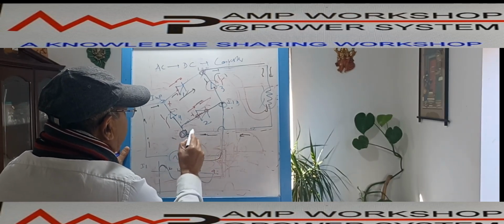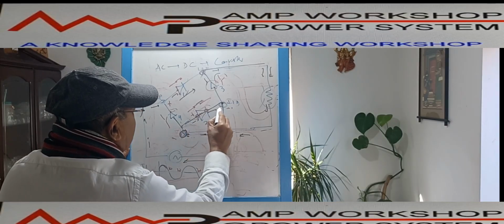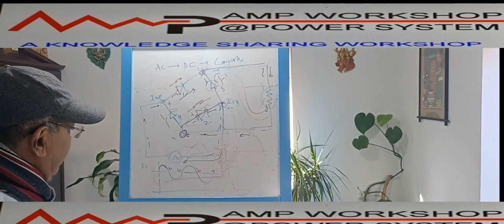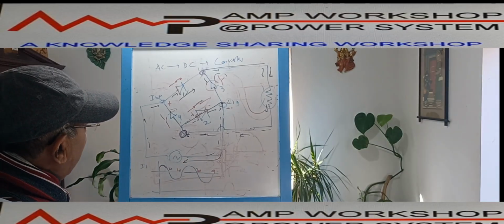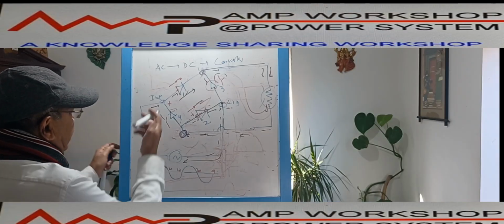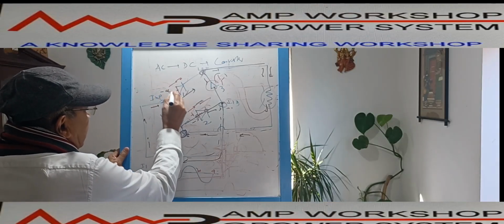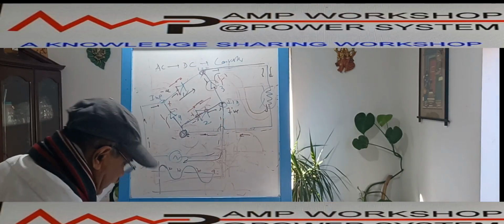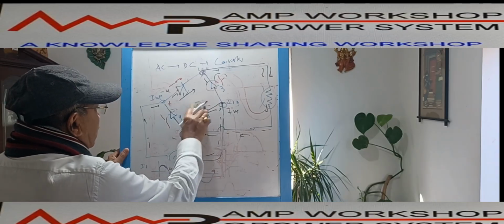It's coming over here. Then it is going through this, it is coming back to the source, first 10 millisecond. After 10 millisecond, what is happening? After 10 millisecond, you see this point become negative, right? This becomes negative and this becomes positive, right? This is positive. When this is happening, then what is the state of the diodes?